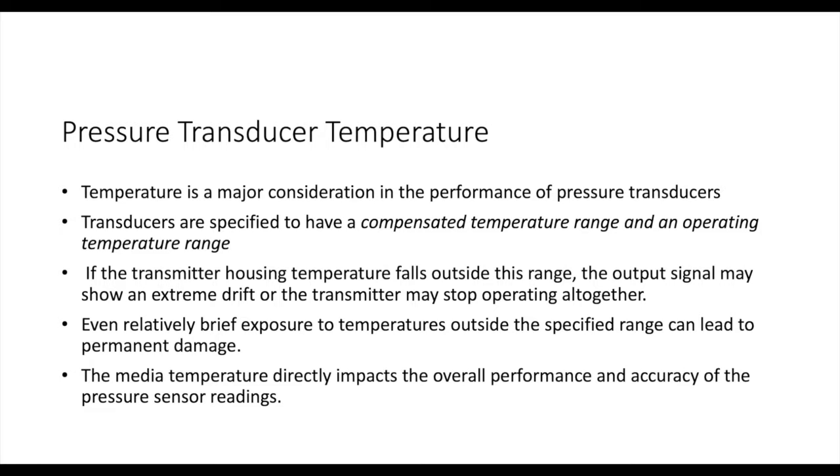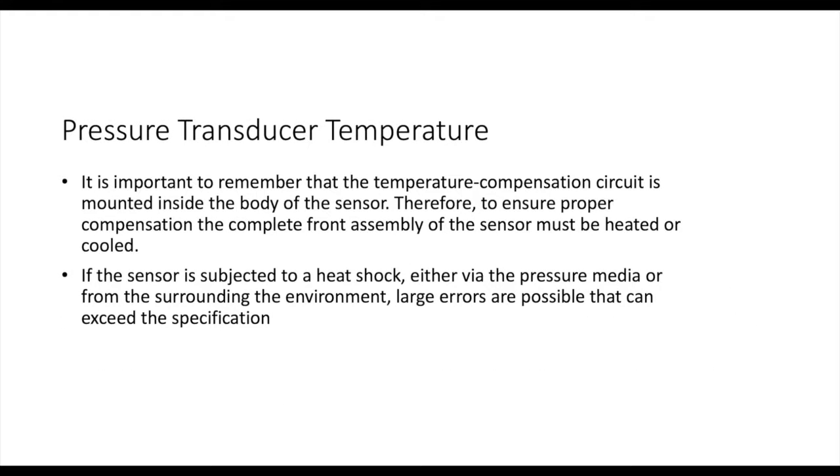It is important to remember that the temperature compensation circuit is mounted inside the body of the sensor. Therefore, to ensure proper compensation, the complete front assembly of the sensor must be heated or cooled. If the sensor is subjected to a heat shock, either via the pressure media or from the surrounding environment, large errors are possible that can exceed the specifications.